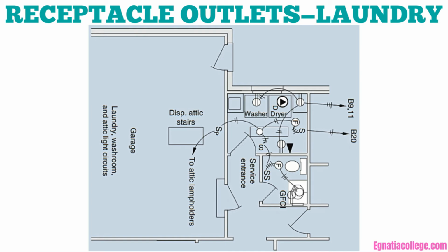This figure shows the cable layout for the laundry room. Circuit B9 connects to the 2 receptacles in the laundry, which will serve an iron, a sewing machine, and other small portable appliances. Circuit B20 has already been included in the watts per square meter calculations for service entrance and feeder conductor sizing, Rule 8-200-1A, I2. See the complete calculations in Unit 7.